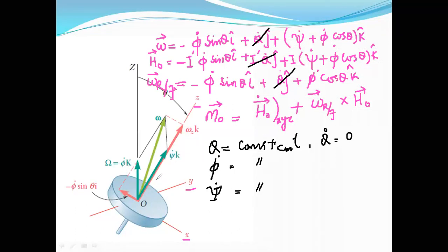See, when you have a steady precession, at that time, the angular momentum of this rigid body remains constant. The angular momentum of the rigid body remains constant in this configuration when its phi does not change, when its psi does not change, when the angle theta does not change. Its angular momentum is the same. Is the angle changing with time? No, certainly the angle does not change with time. So this term is certainly equal to zero for steady precession.